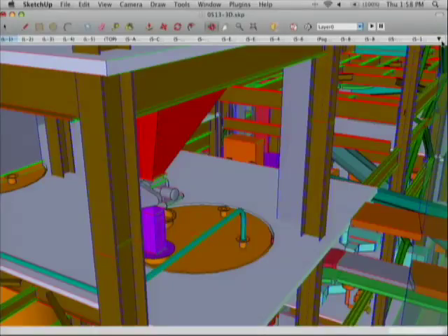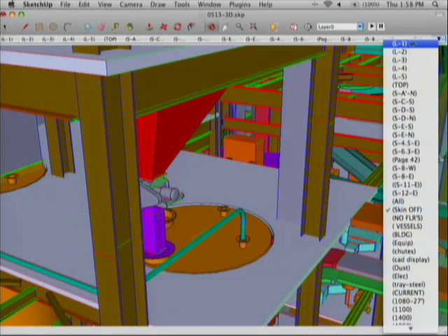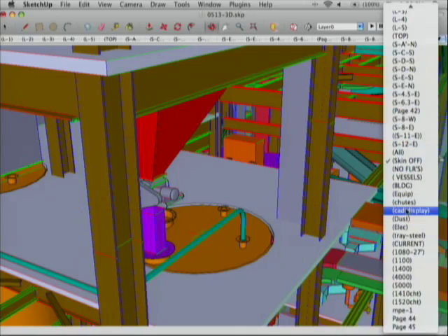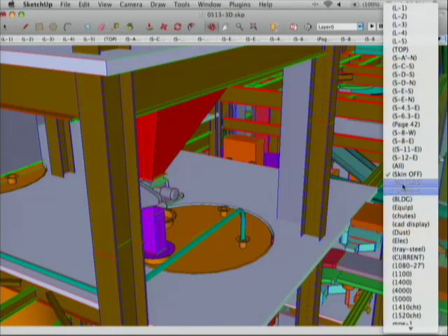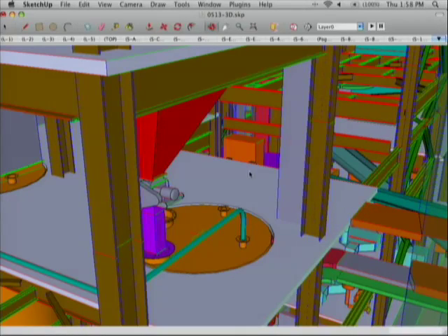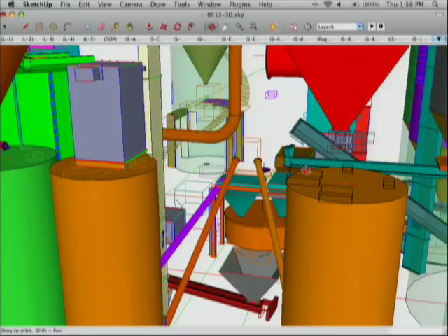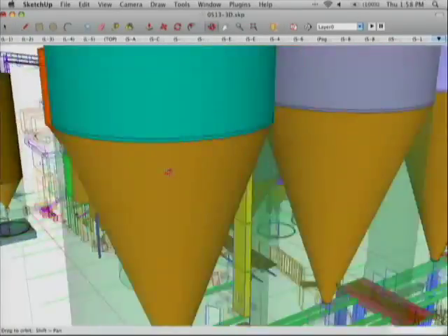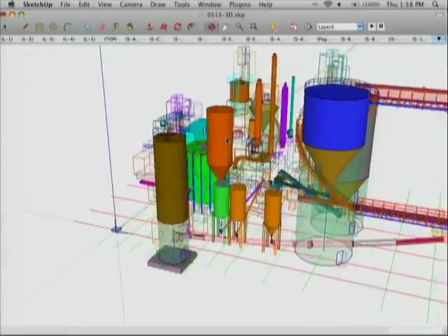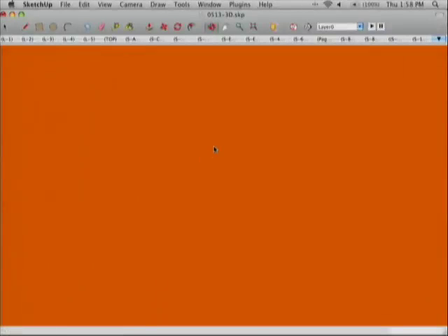What I should do is demonstrate what I'm saying, because what I should do is turn off some layers here. So I told you guys before, this one was done a long time ago, so I don't remember all the layers. Yeah, so what I did is hide all the structural elements of this building. So I don't know how many people have done this. You're within something, you can't get out. If you flip to wireframe, or if you flip to X-ray, you can get out of it.